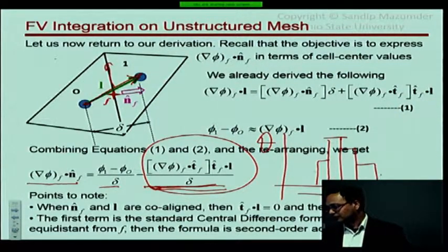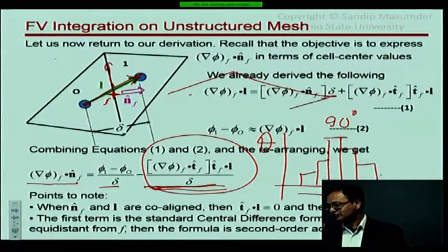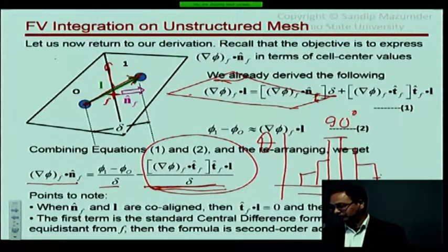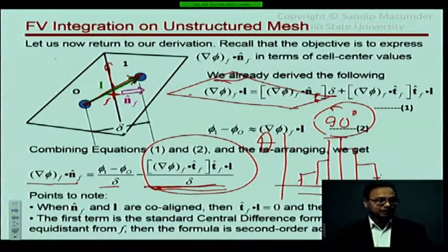And for hexahedral meshes or quadrilateral meshes, you should see a clustering around 90 degrees. Okay? In other words, you don't want quadrilaterals which look like this. That's bad. This is way out of whack, these kinds of obtuse angles or these kinds of acute angles. Okay? They are in the fringes of this histogram. All right? So you want clustering around 90 degrees if it's quadrilateral in 2D or hexahedral in 3D.